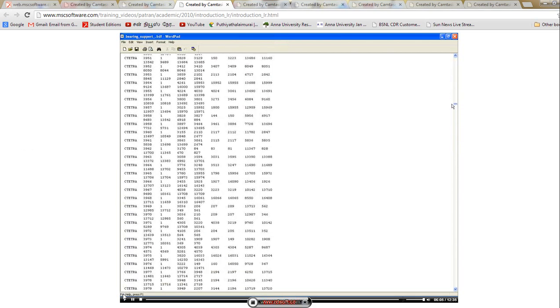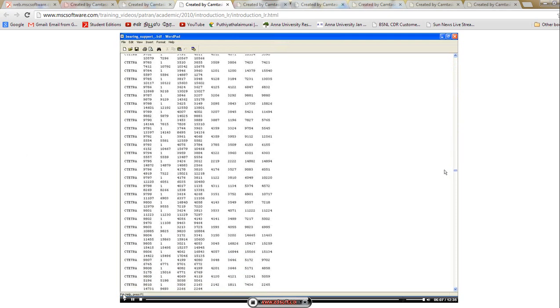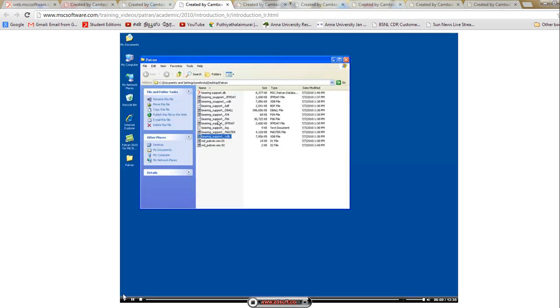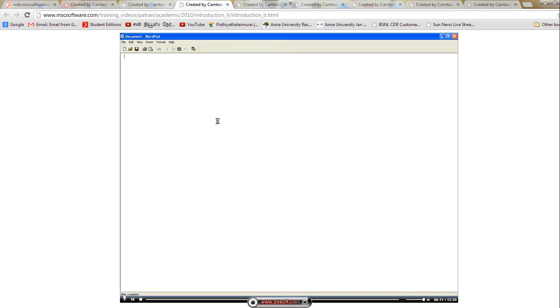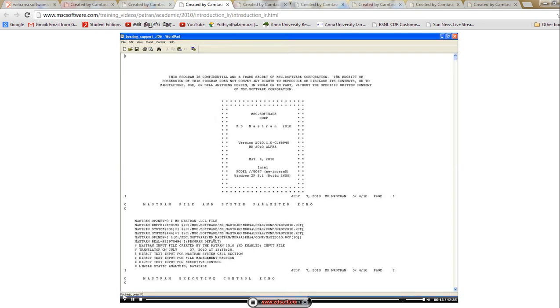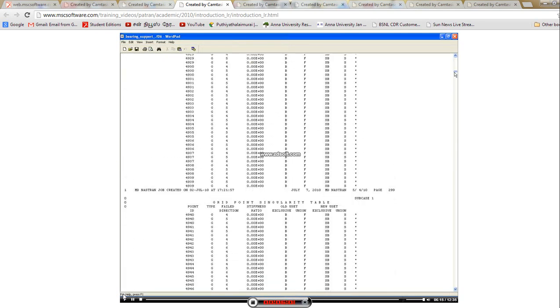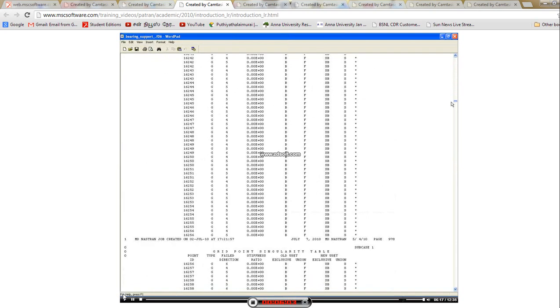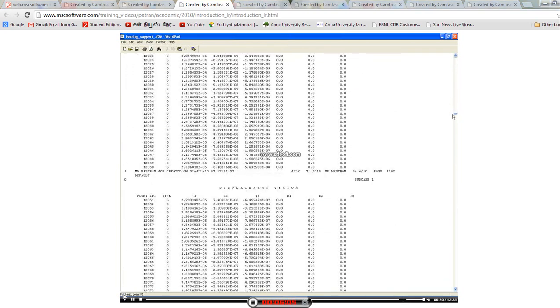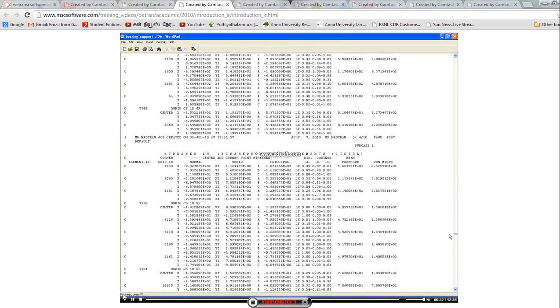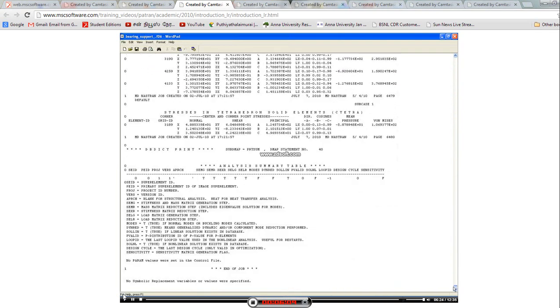The working directory also consists of the .xdb file, the Nastran output database file, which contains the results. The .f06 file will contain all of the information about the geometry and the results. It will also contain any error messages if the analysis did not run properly.